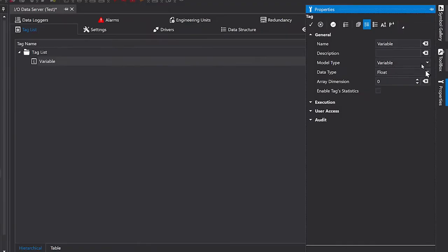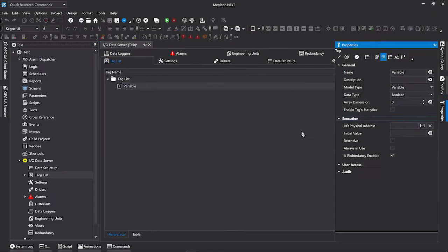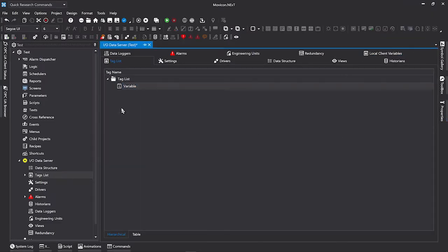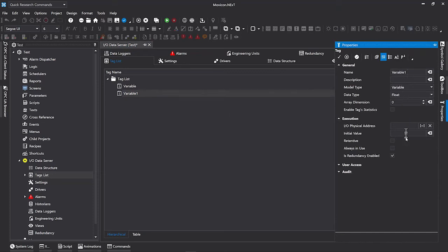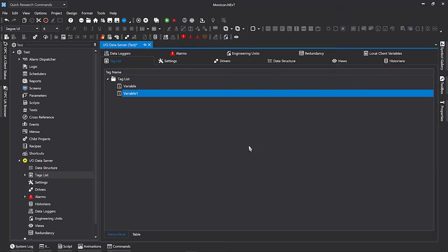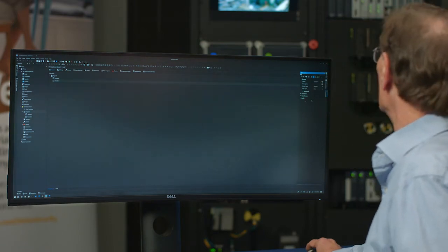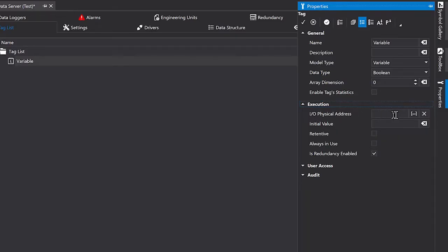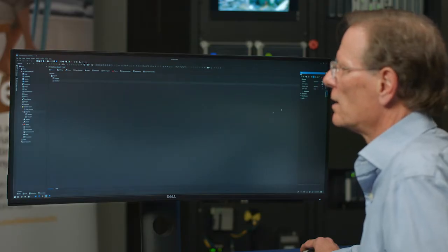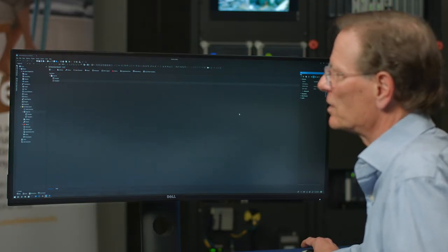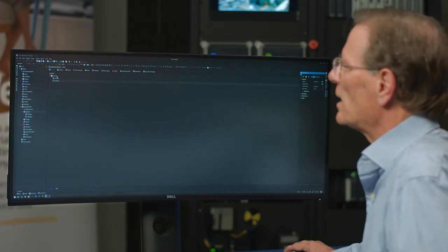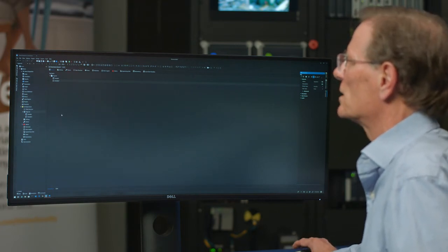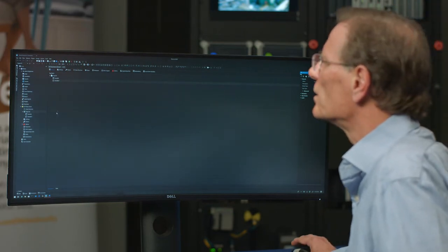And now you can see up here, I have the tag list, and I'm just going to add a new tag. Now for this particular demonstration, the first tag that I want, I would like it to be a Boolean tag rather than a floating point tag, so I'm just going to make that change. So now I have a Boolean tag that I've created. I'd like to create one more. In this tag, I'm going to go ahead and leave it as a floating point. That's going to represent the value in a tank itself. Now, if I was connected to the plant floor equipment, I would actually be able to put in the address either as an OPC variable or other mechanisms that ties it to the PLC that actually is managing that piece. But for now, I've just made these as local variables within my screen itself. That's really all I need to do to create the variables that I'm going to use.